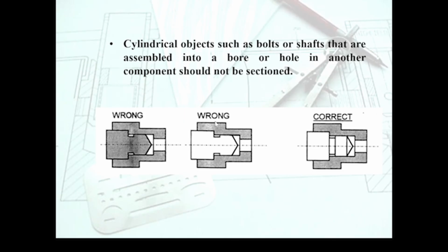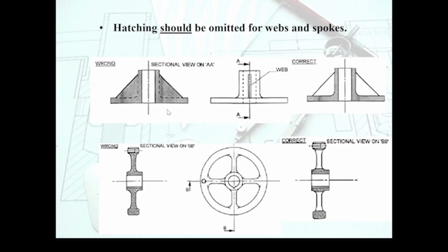One of the other rules around sectioning is, in fact, designed to make it quite simple and quite straightforward, and to avoid creating extra work from the designer point of view and from the reader point of view as well. This is when there are some regulations around the standard shapes, and one of these is basically a spindle. So whenever you have a cylindrical spindle object, we are not going to hatch through that. We are not even going to section through that really. So that's something you want to remember. And there are some more standard shapes where the sectioning rules are quite peculiar.